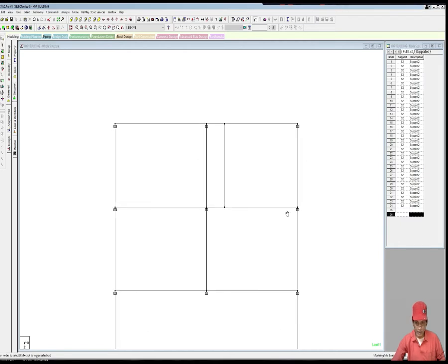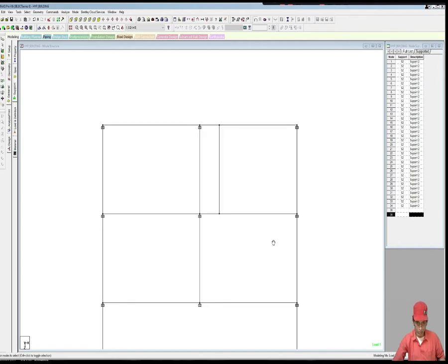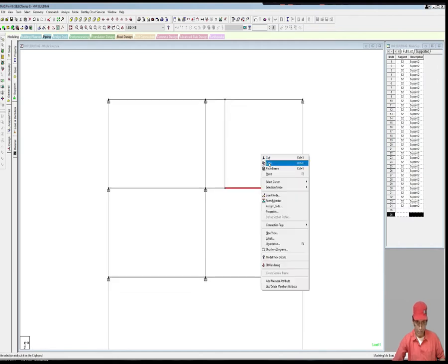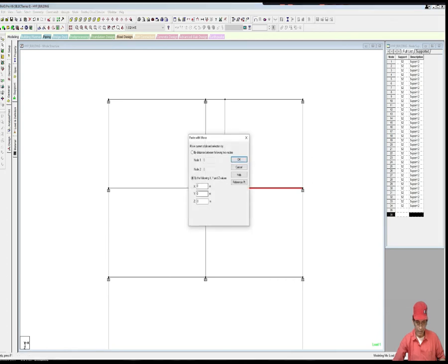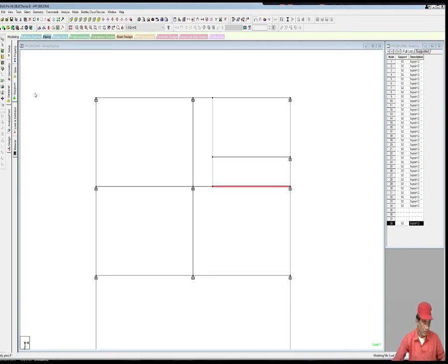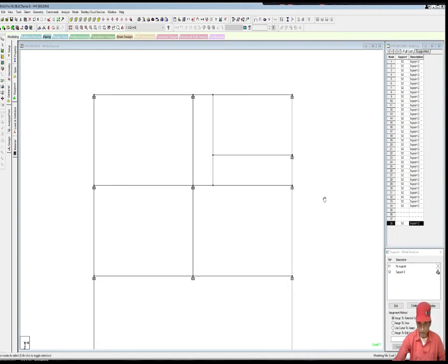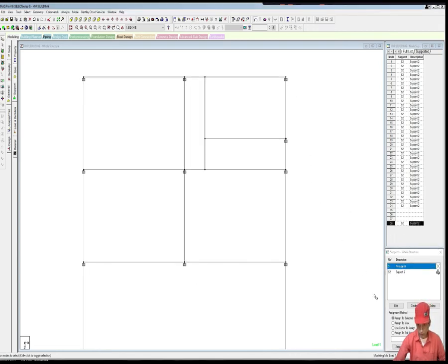Now we need to create another secondary beam to contain the staircase cutout. So we copy this beam, paste this beam by measuring the distance from the architectural drawing. Where is 2 meter? It comes out to be around 1.33 meters in minus z direction. Okay. So another secondary beam is created. There is no column here. So I again assign no support here.